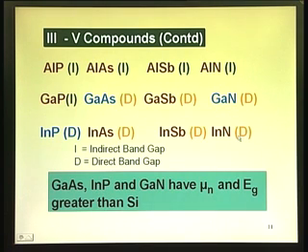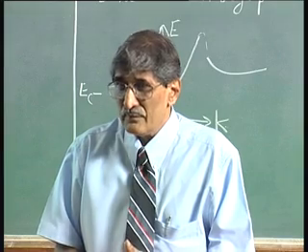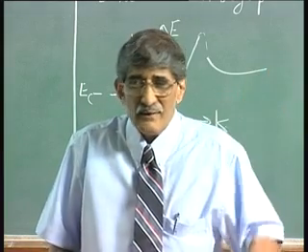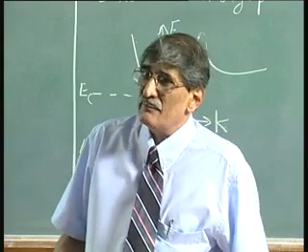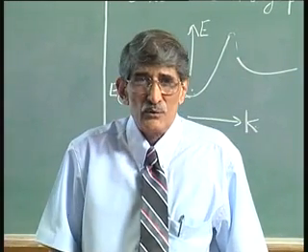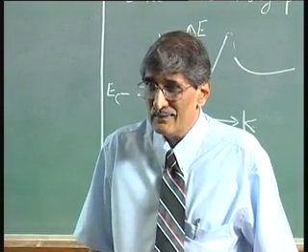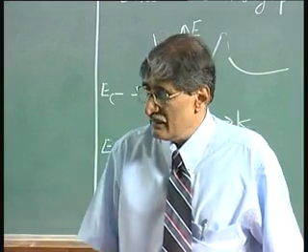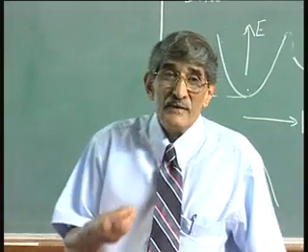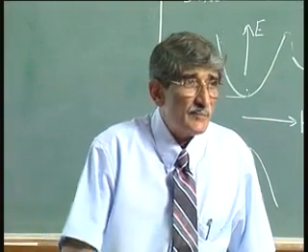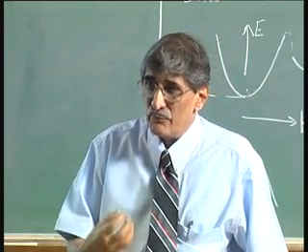Indium nitride, if you take a look at the band gap, people talk of a wide range. Recently they have started talking about a band gap of about 0.7 electron volts. It was much smaller earlier. The whole range has been reported, which means people are still working on purifying those materials.